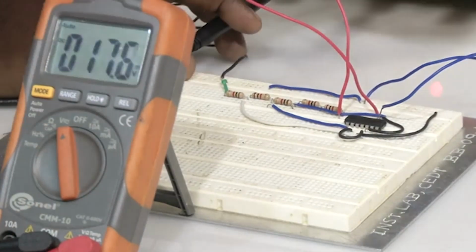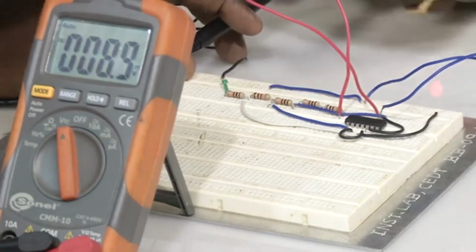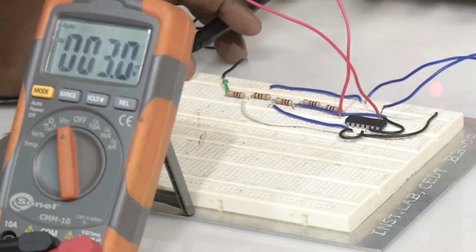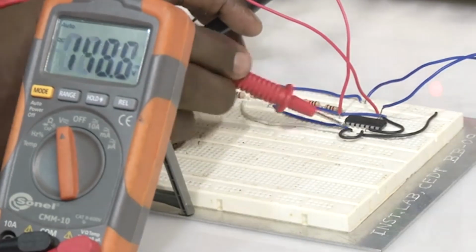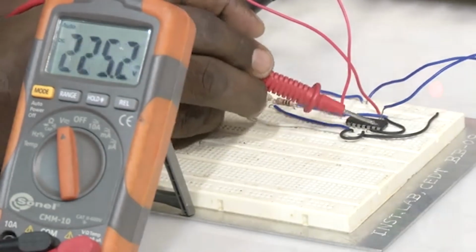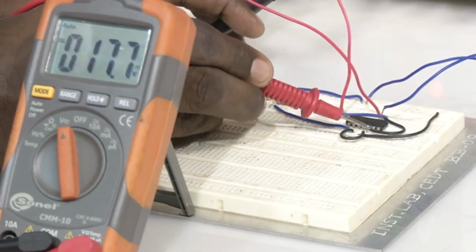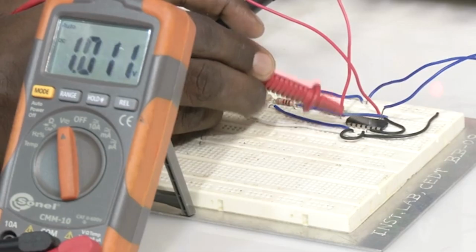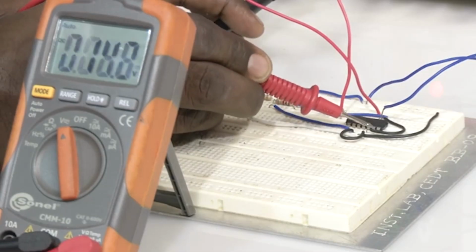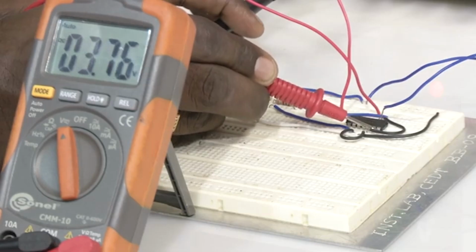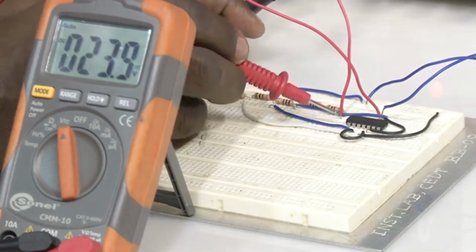Now, let me increase to more than 3. So, anything more than 3. Since we have chosen as 3.5, let me take it as 3.5 itself, easy for us to understand. So, observe from first op amp, this is 3.5 positive terminal, negative terminal is 1. So, what about this value 3.6, which is plus VCC. So, that means C1 is higher.